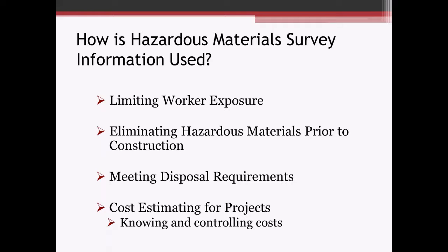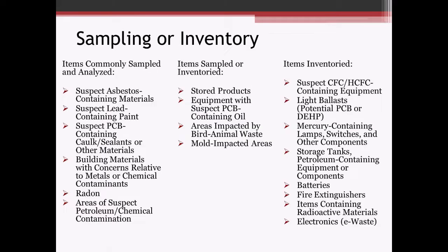Meeting your disposal requirements, and then also cost estimating for projects, knowing and controlling your costs. If you have your hazardous materials survey done up front and you've got good comprehensive information, you can estimate how much it's going to take to remove those materials, dispose of them, and not have as many surprises later on in construction. We all know there are things that pop up during construction that were unforeseen, but the more information you can have up front, obviously the better to keep those costs down.